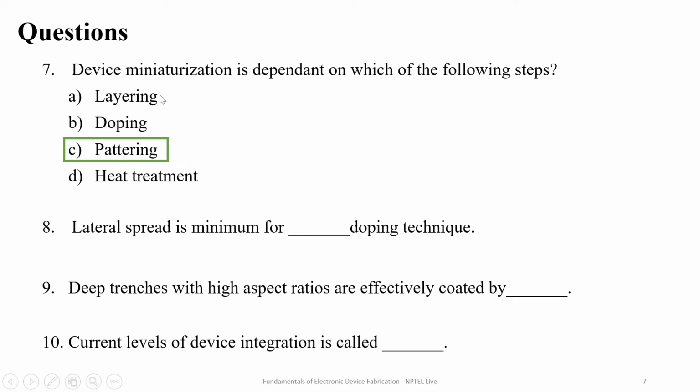Yeah, so functionalizing an IC is done by patterning basically. How small we can make a particular pattern determines how small the functional units on an IC can be. So during patterning, first we deposit an oxide layer, and then we place a pattern that is actually a copy of the circuit that we want. Then we apply a photoresist and irradiate it with light. The portion covered by the photoresist won't be functionalized, and the rest of the regions will be. That is how we make different gates, sources or drains in an IC. So that is the patterning step.